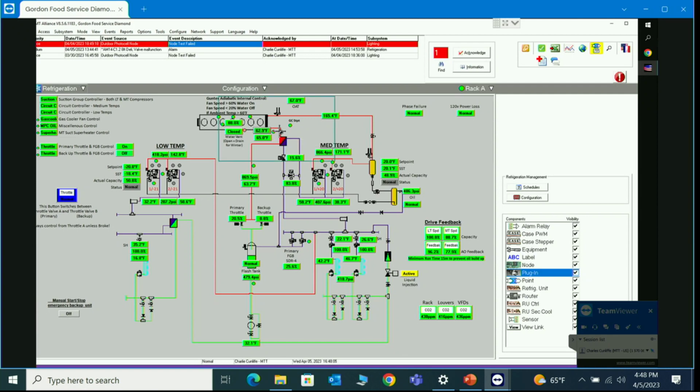gas cooler. I come down through a heat exchanger, and here's my drop leg. My drop leg, take my word for it, is 869.5 pounds, 63.5 degrees. And there's my throttle valve, the LMP calls it, or the high pressure valve, or I call it the gas cooler valve. It's right now 20% open, all right? They decided they wanted to have backup valves. So they have redundant flash gas valves and they have redundant gas cooler valves.